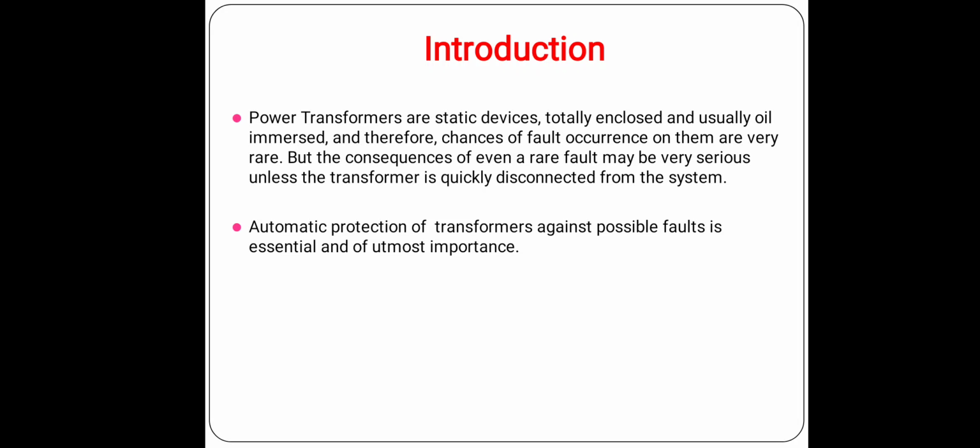Rapid reclosing of circuit breakers is feasible on lines and it helps in saving the amount of damage, while a fault in a generator transformer always requires some attention of the supervisory staff. Fast clearing of faults, however, assists in reducing the damage to the equipment and also reduces the interruption in power service caused by drop in voltage and from instability.